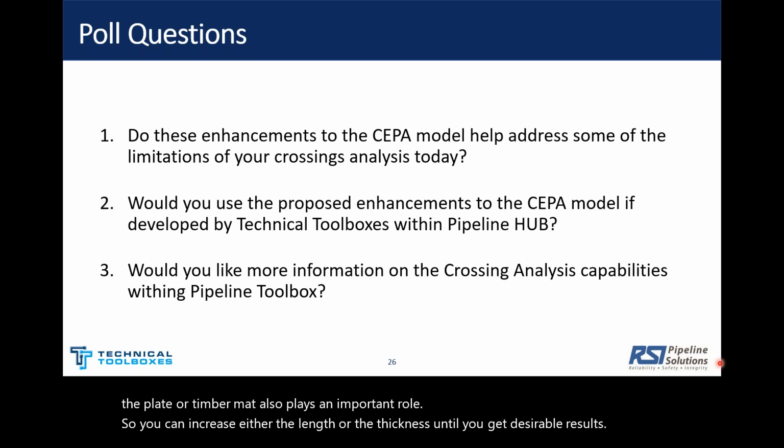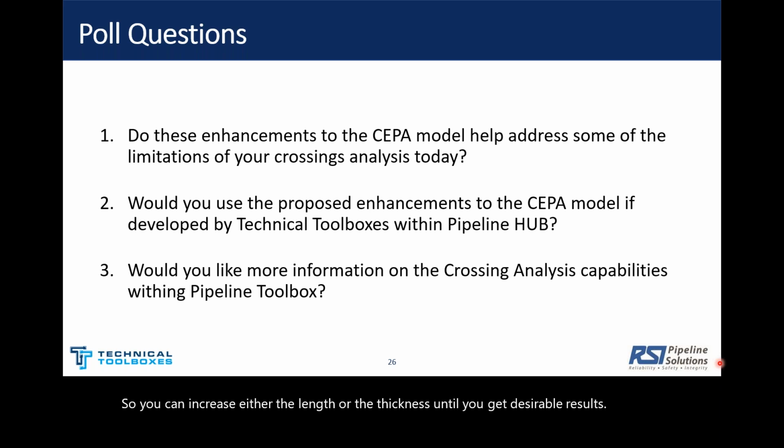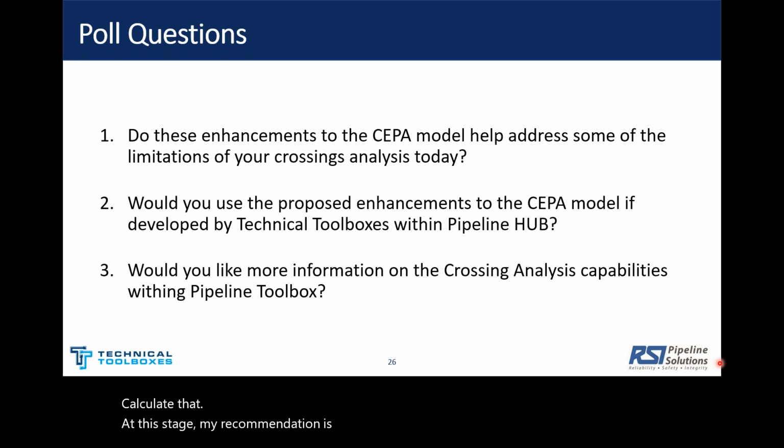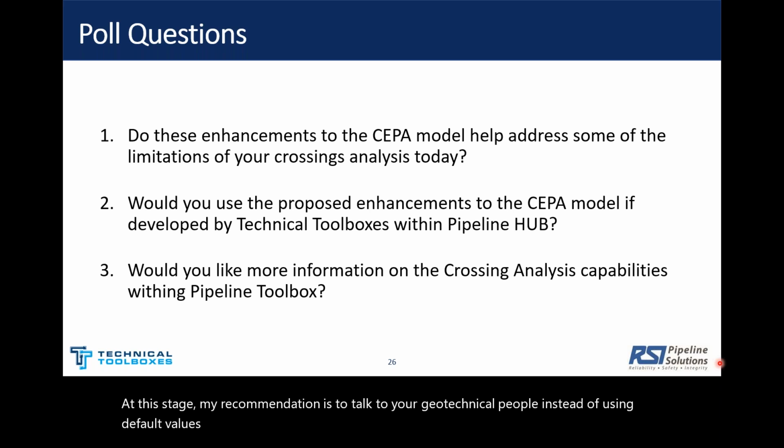Okay, is there any assumption or drop-down list for the K0 lateral soil pressure coefficient for different soil types? Yes, there is a way you can calculate that. At this stage, my recommendation is to talk to your geotechnical people instead of using default values. But if you want to use a default value, you can find some recommendations in soil mechanics books.